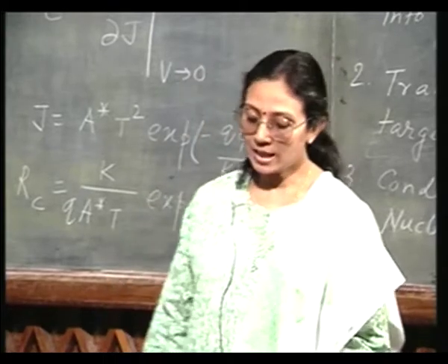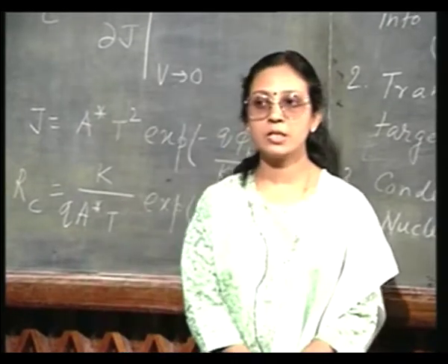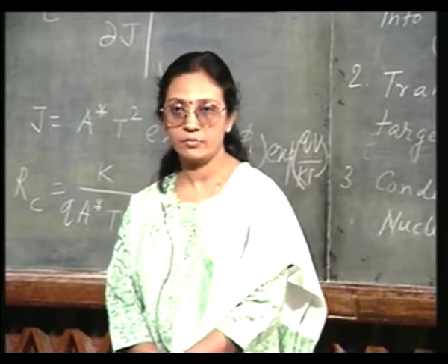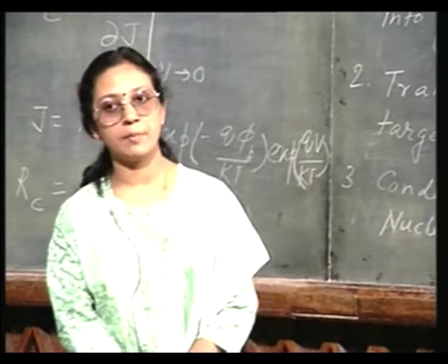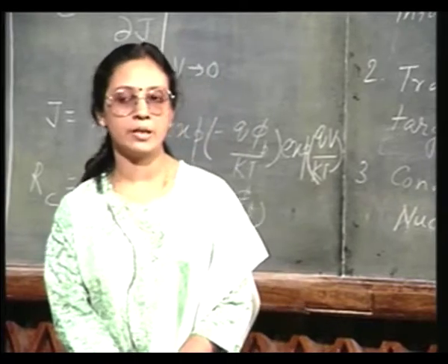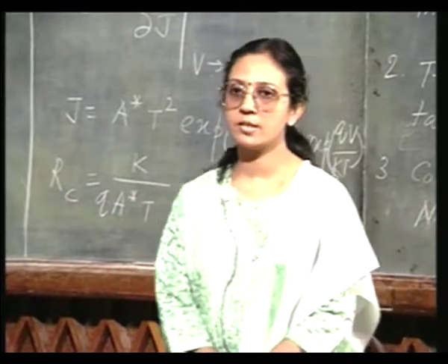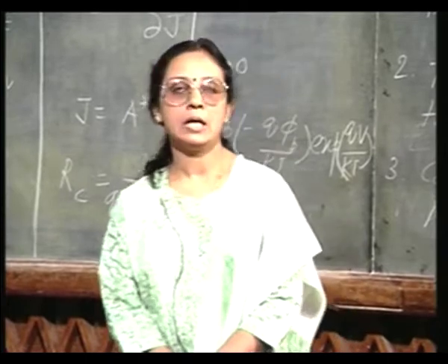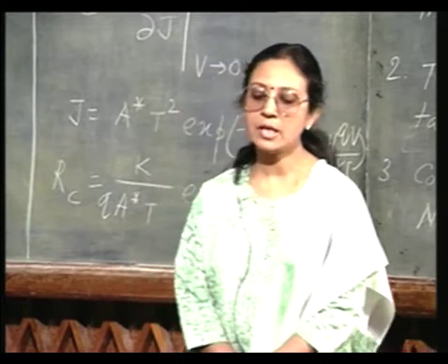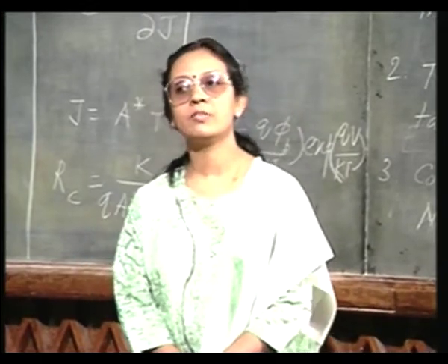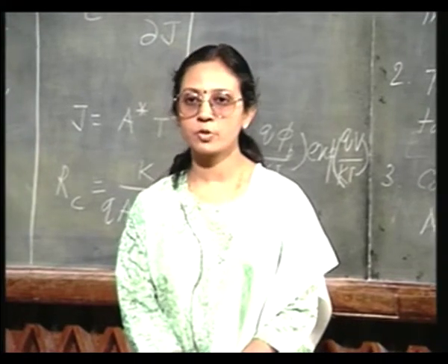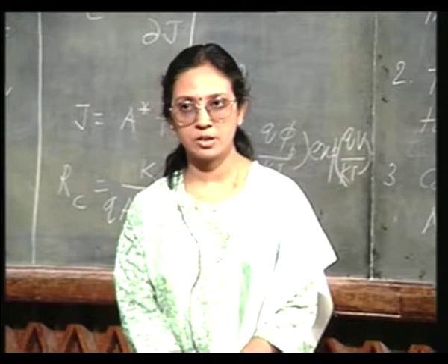But sputtering will have a little bit of problem. You see, you are using high energy ions to bombard on the substrate. Therefore, there will be some amount of ion damage, which of course can be annealed out. Annealing temperature also is comparatively low, less than 500 degree centigrade, these damages can be annealed out. The other problem is, unlike in vacuum evaporation technique, in sputtering technique the pressure is usually comparatively higher. Therefore, the films will have some trapped gas, also possible to have some trace of contamination in them.